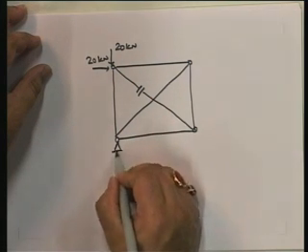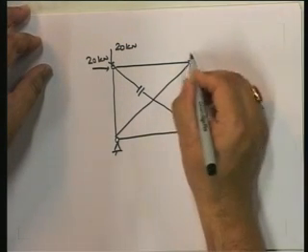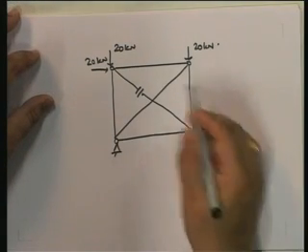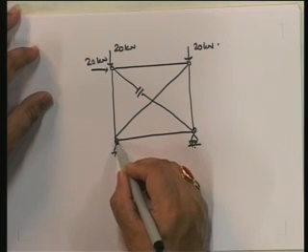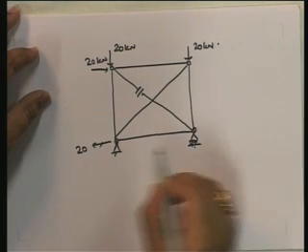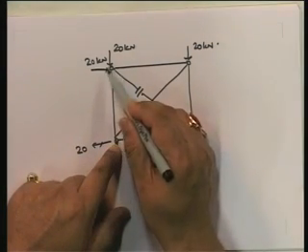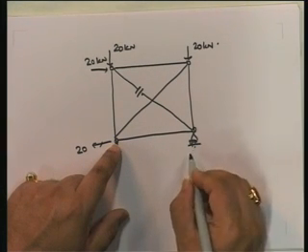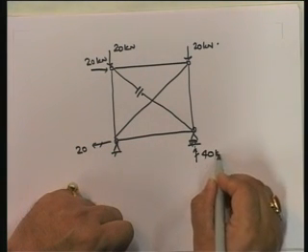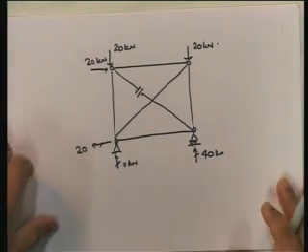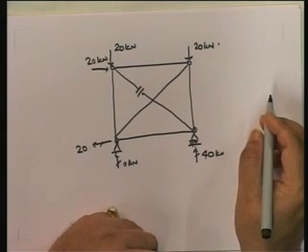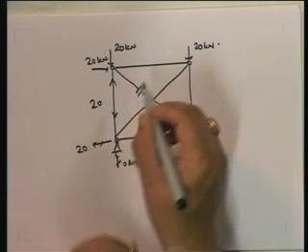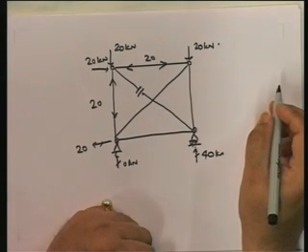So I am going to just solve this problem to begin with and get my SI0 for each one. I am just going to forget it at that point of time. Okay. And therefore, let me solve for this. What am I going to get? If I take, here, this is going to be equal to 20. Then if I take moments about this point, I will get 20 into 10, 200, plus 200, 400. 400 divided by 10, you get 40. And this is equal to 0. Okay. So if I have this particular situation, since this is 0, I can find out that this is going to be equal to 20. Similarly, this is going to be equal to 20.